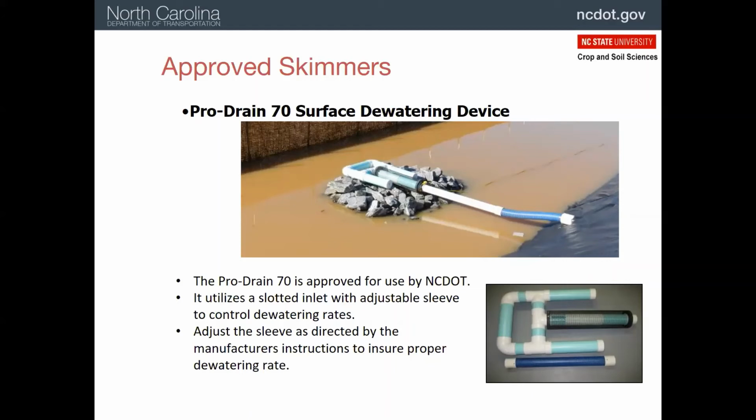And then thirdly, if for some reason the skimmer is not on rocks, it will end up floating and it won't get stuck in the mud. So we have quite a few reasons. Also note here we have a rope. So all skimmers are going to need to have a rope attached to them so that if and when this screen gets clogged, then we can pull it off to the side. So make sure there's a rope that's staked off to the side.